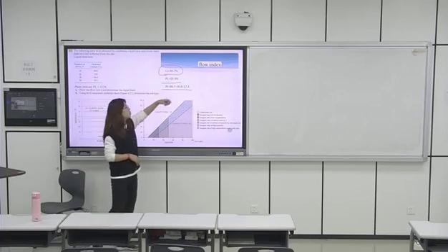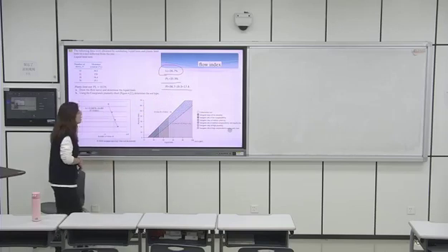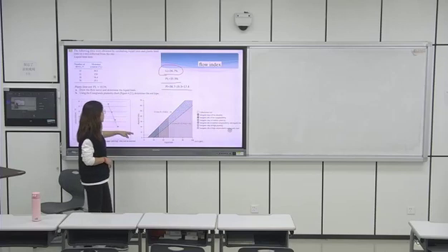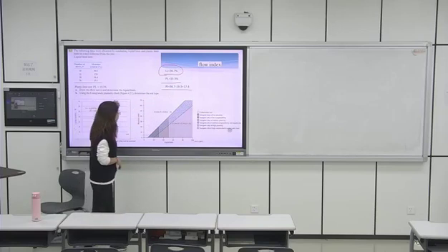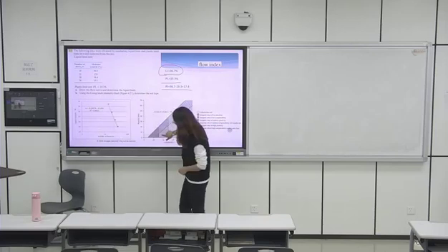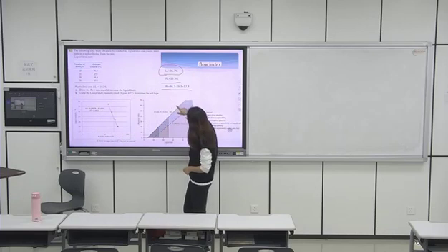This is why we calculate the plastic index in here. So we got the plastic index and liquid limit, and we can locate the soil on this chart. The liquid limit is around 36.7. 30 is around here, 36.7 is around here. And the plastic index is 17.4.